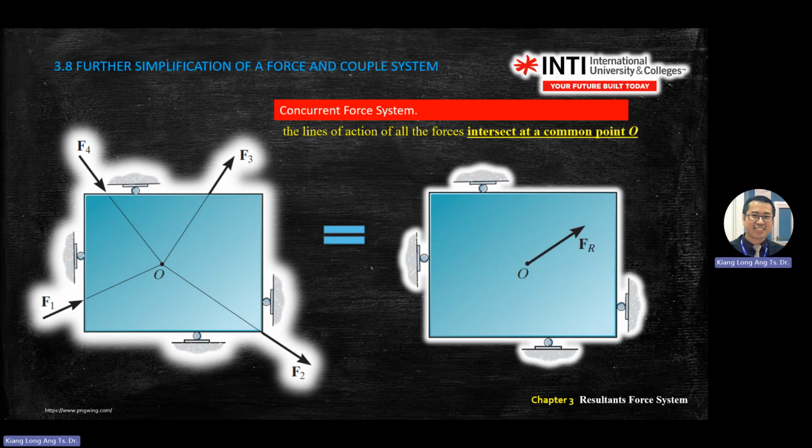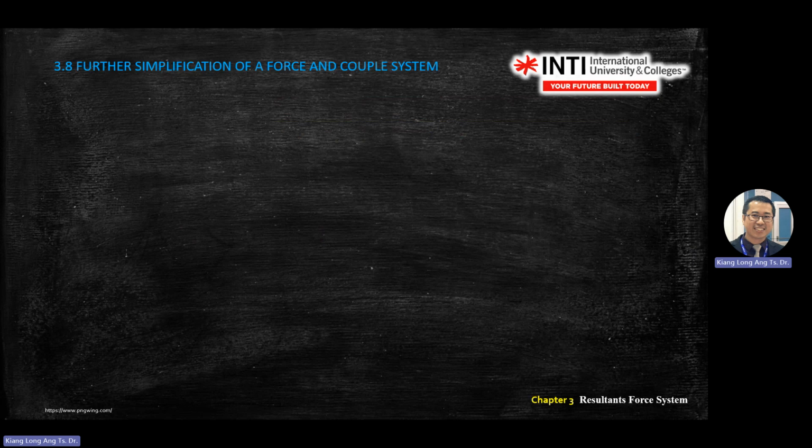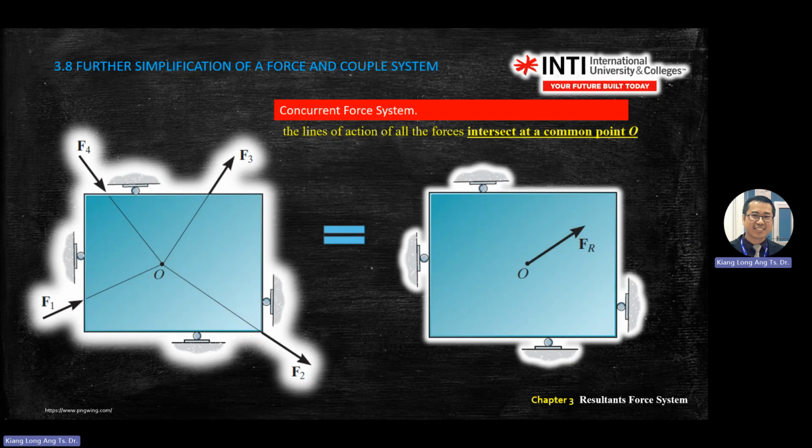Yeah. Means you can transfer the force along an axial line. You just draw a simple line from F to the focus point that you want. Or you draw a line and then join the intersection point, transfer all the force to that. Right, then you get the resultant. Why no moment here? No perpendicular distance because you are actually moving the force along the line. You can move the force along the line.